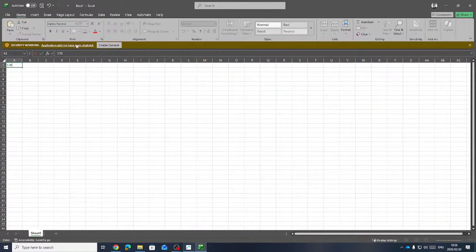So you have a surface bed, which bears on ground. Then you've got a slab above, a concrete slab, maybe in a parking deck. That needs to be a certain thickness. Then you've got a bigger coffer slab, that's a transfer slab, where the grid can change. You learned that today, it's a big thick slab, and then above, we're going to go timber. The best example to see this in reality is go to Loftus, go into the parking underneath and have a look. You see how the grid changes, and there are massive transfer slabs there and beams. That's where you understand what's involved.